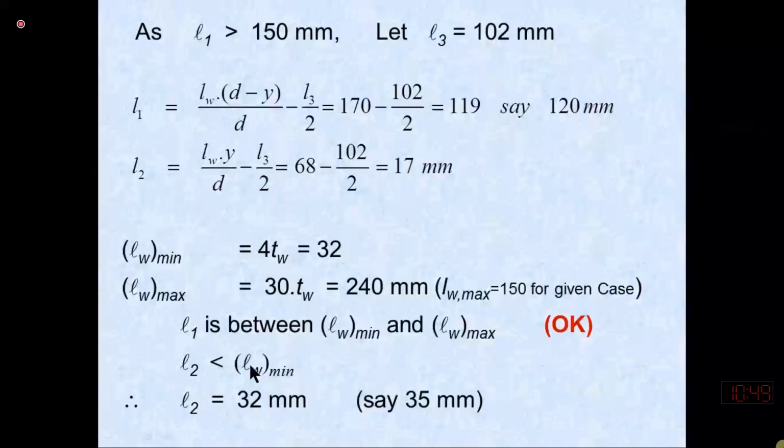And then at the end, you need to show the weld on a neat sketch like this, showing proper standard designations. So you will sketch this, and L1 is provided on the thickness section. So this L1 is equal to, sorry, here I have reversed it, but I will correct it quickly. So this weld is supposed to be 102, sorry, 120.